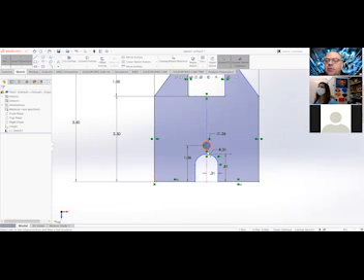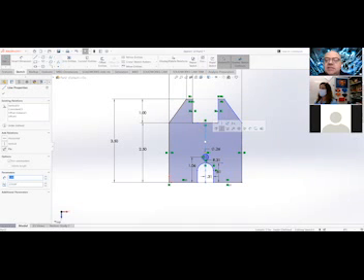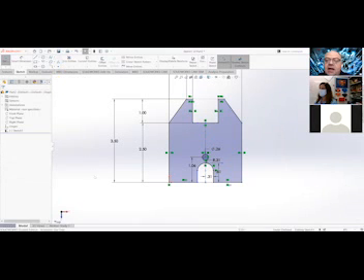Now, you noticed how when I was moving this circle, my center was moving. That's a scary thing because that's what's kind of holding my top together. That is a really important line. Because I made that mistake, I'm now scared for you. If you select that line, this is an example of where you would lock in the anchor and fix it. So now that cannot move.